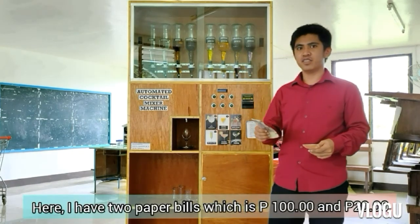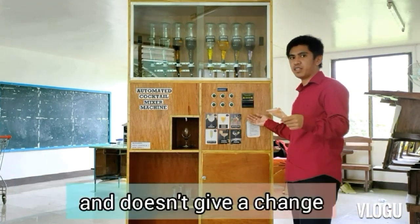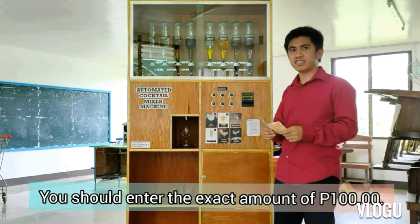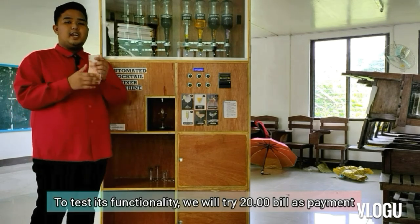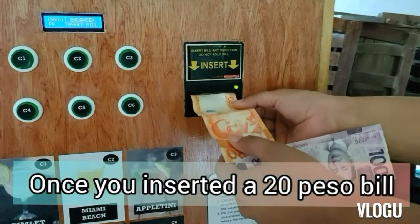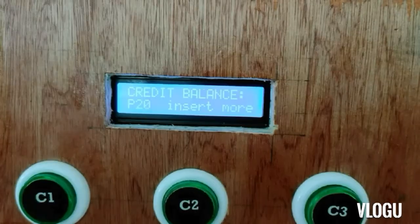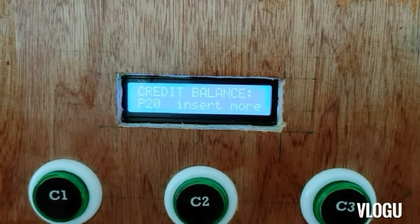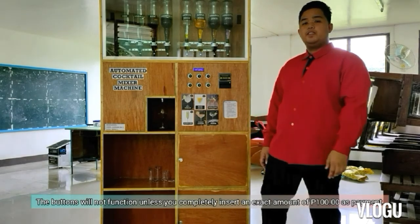Here, I have two paper bills, which are 100 pesos and 20 pesos. This machine only accepts paper bills and doesn't give change. So when you want to choose your desired flavor, you should enter the exact amount of 100. To test its functionality, we will try a 20 peso bill as payment. Once you insert a 20 peso bill, the LCD screen shows that you need to add more bills to process your order. The buttons will not function unless you completely insert 100 pesos as payment.